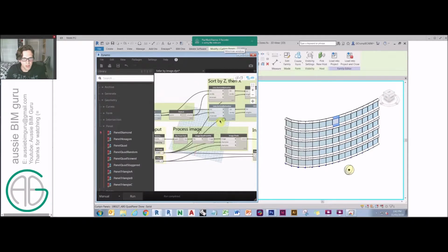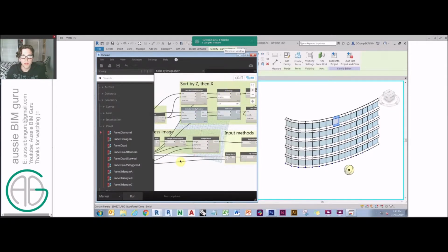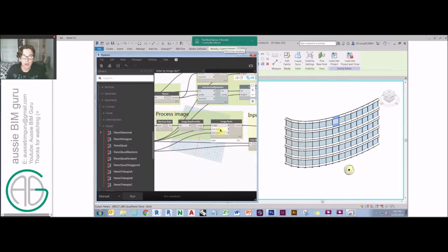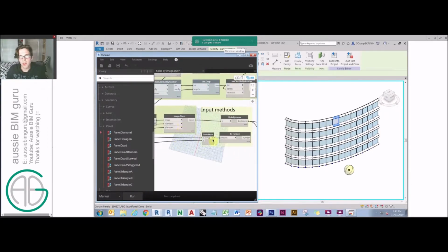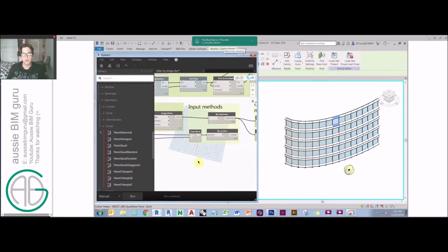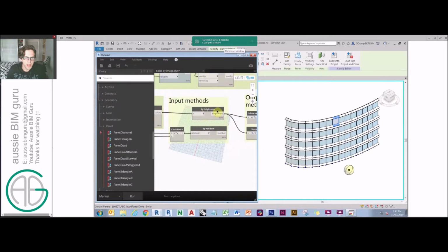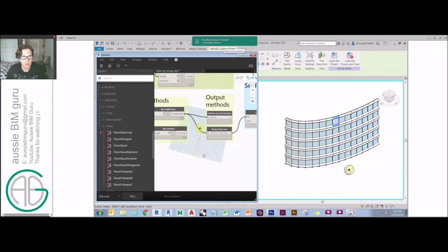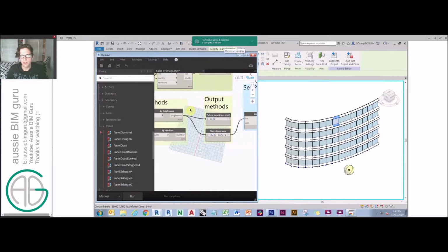And then I'm feeding these basically up here to chop the lists into rows, but I'm also using them to take that image and divide it into samples or pixel samples along that image. So I can basically pick at which moment in the image each panel should be corresponding to, because from there I'm taking the brightness of that image. I've set up another alternative option I'll show you, which literally randomizes the numbers. And I'm either going with half of that from 0 to 1 to map it to a 0 to 0.5 range, which is basically inversion where it will follow the sun.